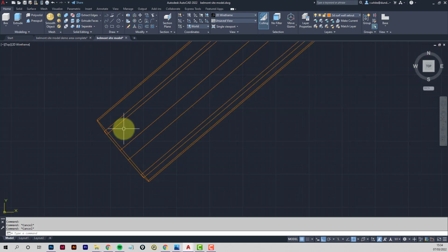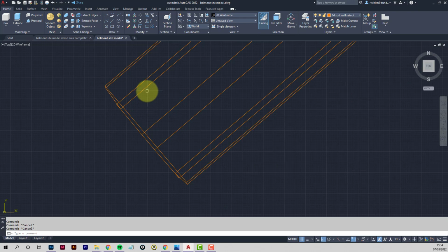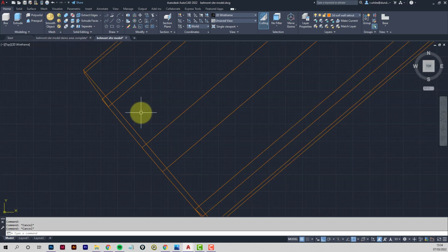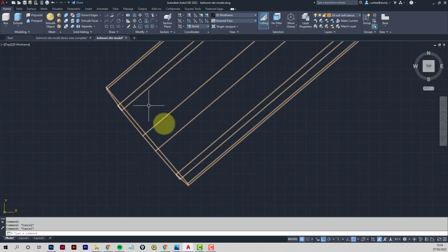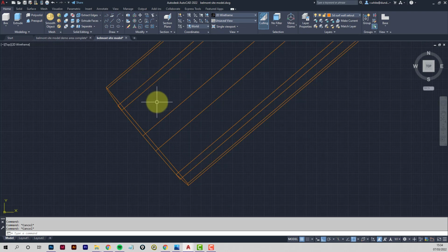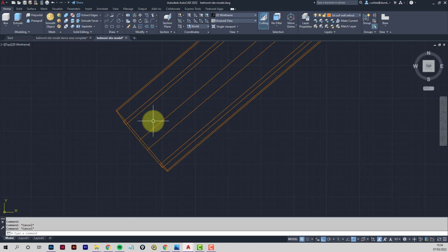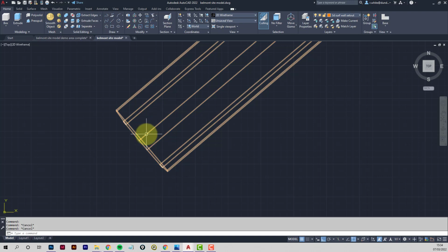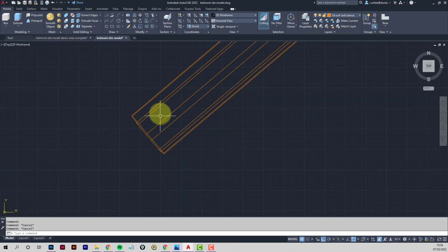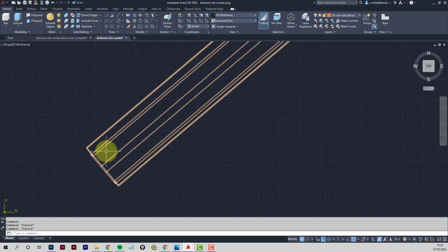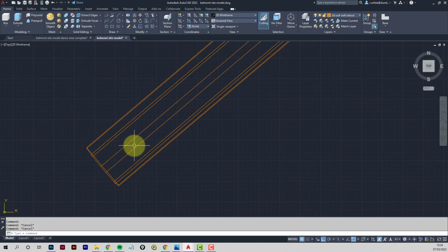Okay, if you look at the end of the sweep on the 3D polyline, it's not looking so good. They've got different gaps. We've got different gaps showing up everywhere. So that means that this wall is tilting as well. It's leaning outwards or inwards. It's hard to tell which direction. So things aren't great. It's not a huge amount of tilt because the landscape here is quite gentle.